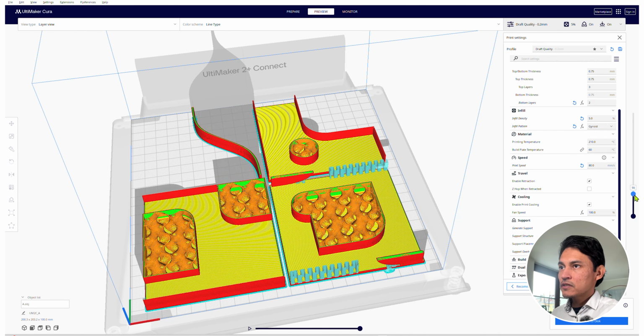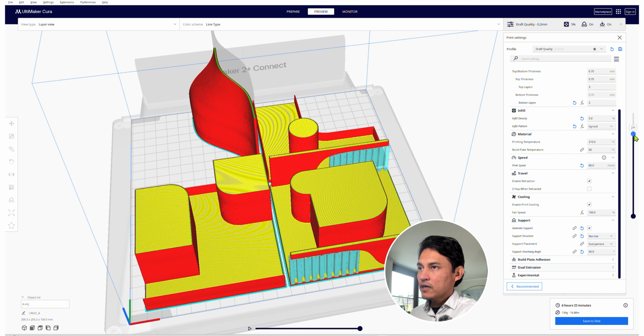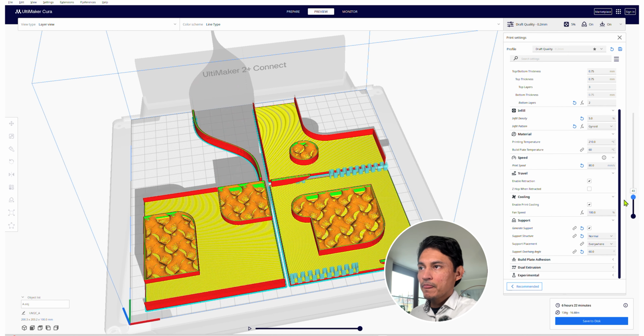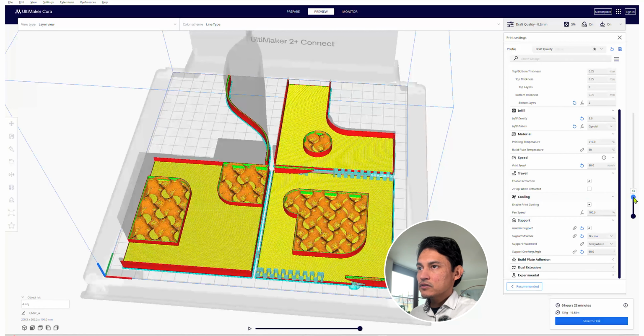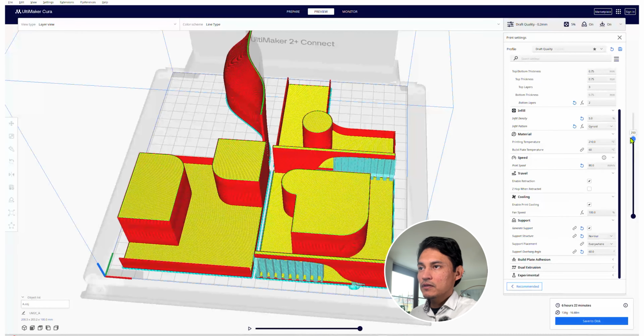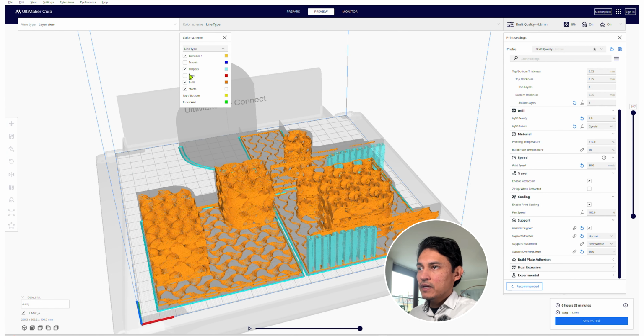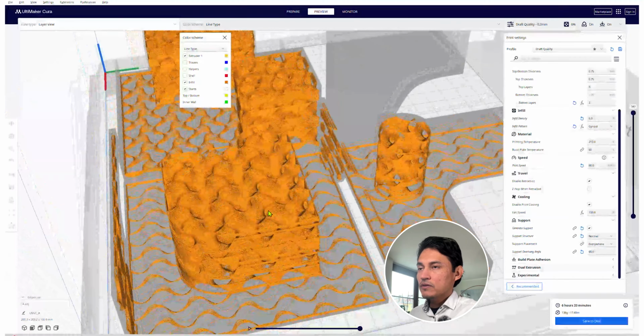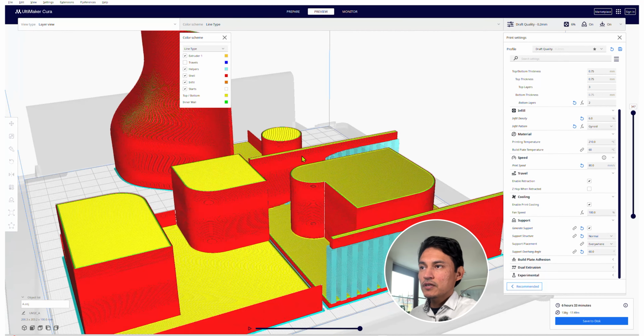Again, 3D printing is a slow process, but by choosing the gyroid infill you can save some time. Because of its minimal surface structure, it provides sufficient stability with continuous surfaces, making it relatively faster than other infill types. I'll show you here.